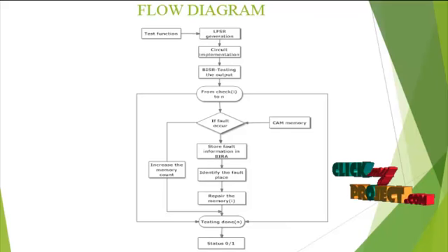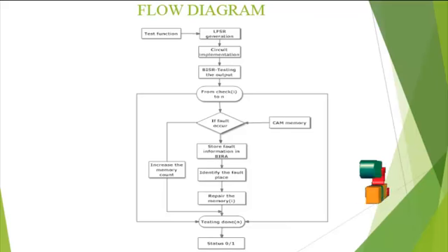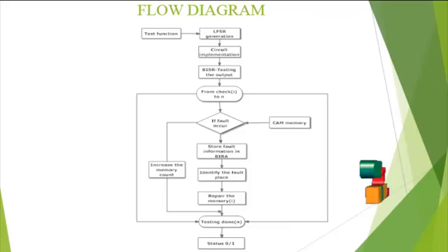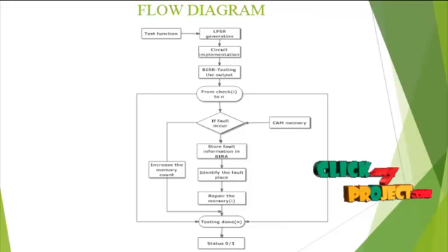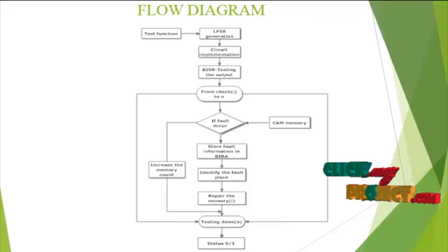When the signal test_start is asserted, TAG and TPG generate test patterns and test addresses for executing the adapted march test algorithm. The overall test procedure is controlled by the signal test_control. The clock and reset signals are provided through clock and reset. The CMP compares the results from the memory and expected responses to detect faults.